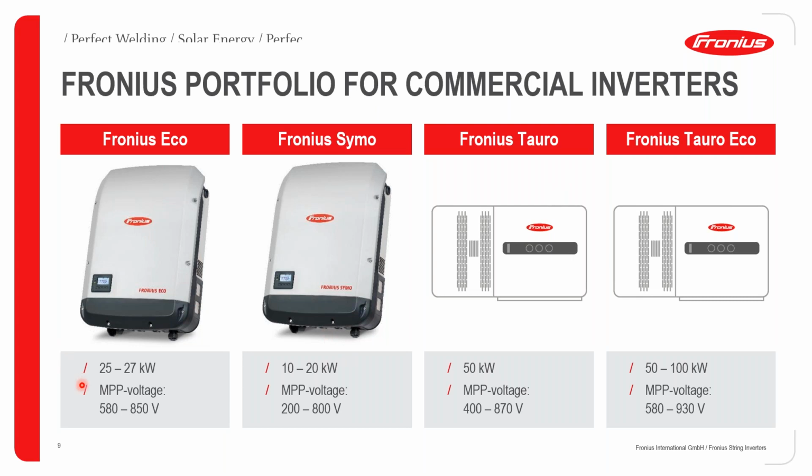Beginning with the Fronius Eco, that comes as a 25 or 27 kilowatt variant, and your MPPT tracking voltage range is between 580 to 850 volts. So whenever you're planning your strings, please make sure that your voltage per string is somewhere within this range to ensure the optimal performance from your inverter.